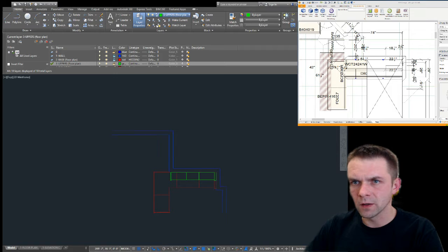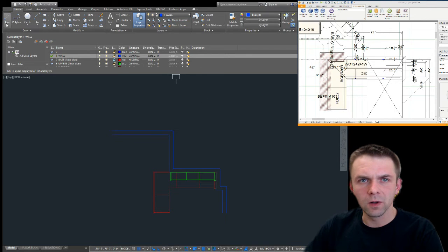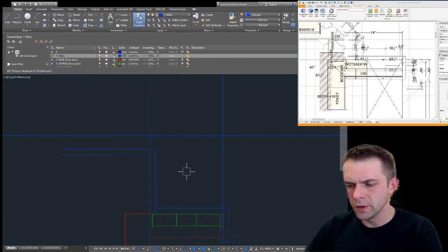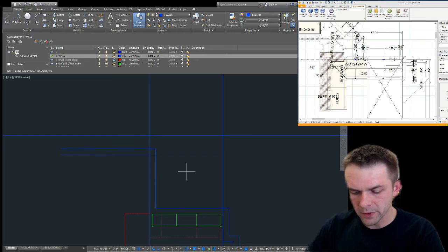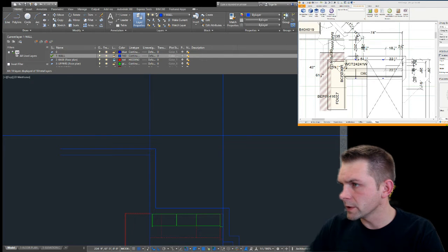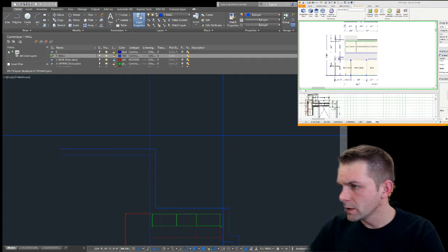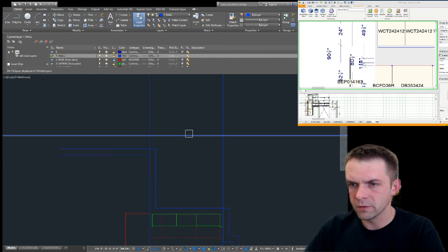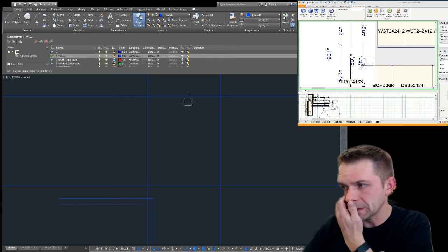So first we unlock the wall, select the wall cabinet, go to draw, select the vertical, D for vertical space, and then just click at the end points for now. So we're doing this wall, again looking at my measurements, or looking at my 2020 design, the wall is 90 3/8. Offset 90.375, and that's that.